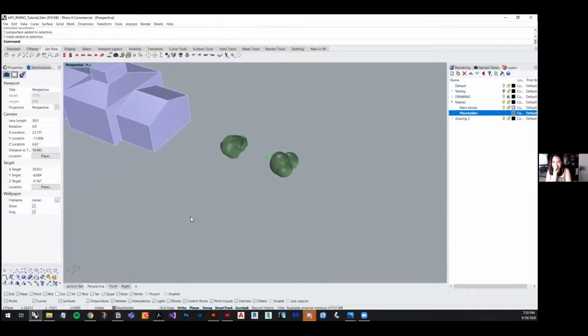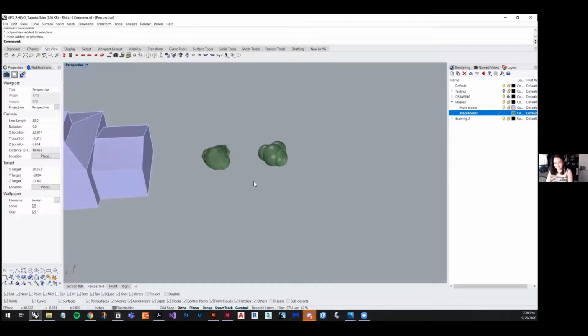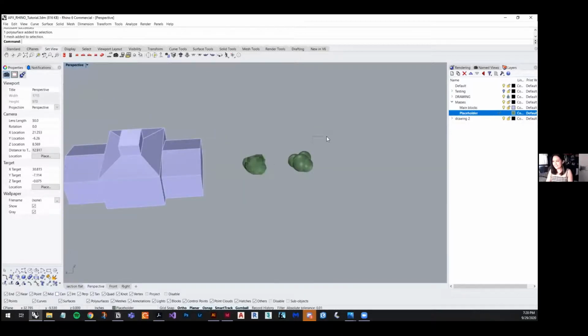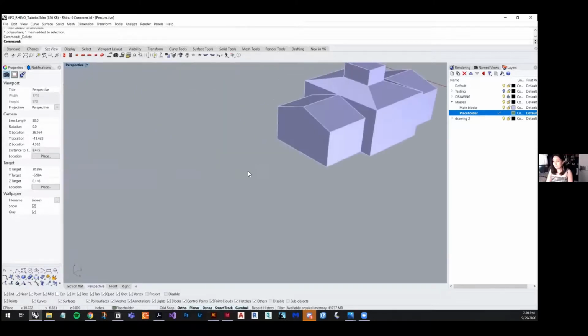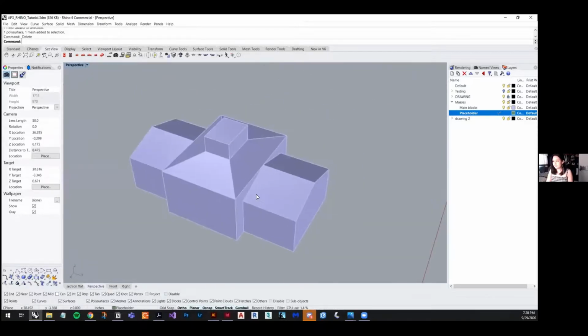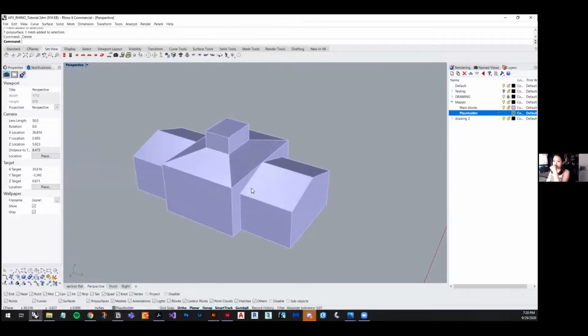I don't know if we have any questions, but I'll give my secret tip that people always seem to forget: people outside of college at UH love to 3D model and will put their 3D modeled objects online. So sometimes if I'm in a last minute rush and I don't want to create my own trees or shrubs, I'll literally go onto Google and type in shrub STL model free, or tree STL model free, because normally people who 3D print stuff upload their files as STLs.